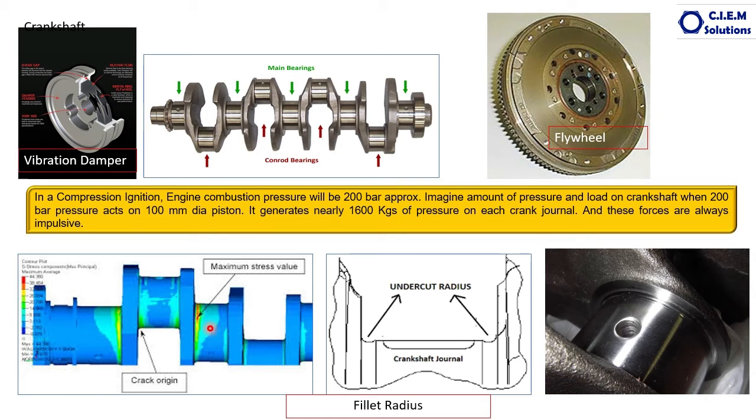So to absorb those impulsive forces and also to distribute the stresses, which are concentrated here, you have to distribute the stress and increase the fatigue handling capacity. So you are increasing the surface area here. From a sharp edge, you are making it a slight curvature and giving a small dip cut, a small undercut here. This is a big engineering design.